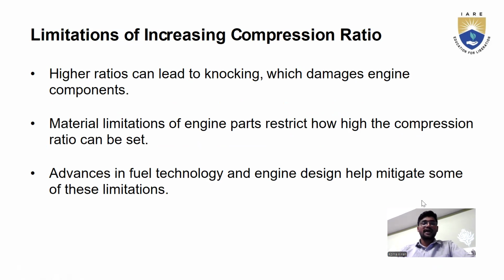Now, limitations of increasing the compression ratio. If the compression ratio leads to knocking, it can damage the engine components. That is a limitation. The other thing is that the materials of the engine parts restrict how high the compression ratio can go.